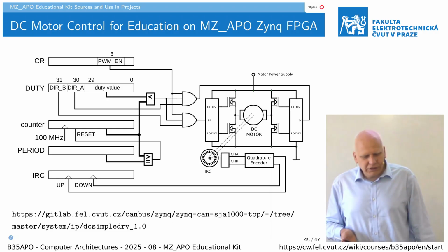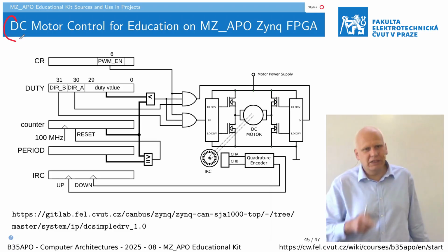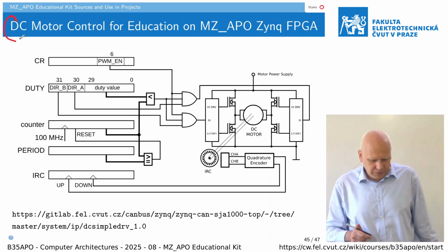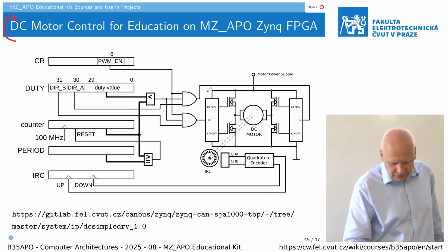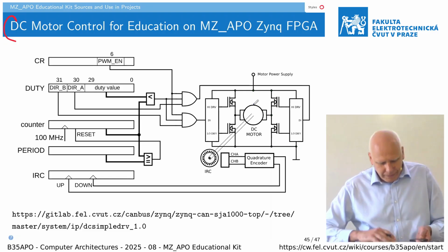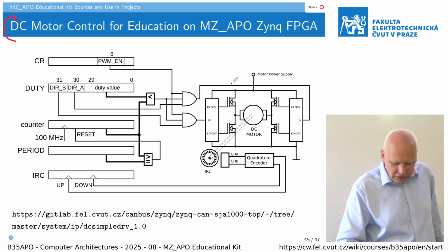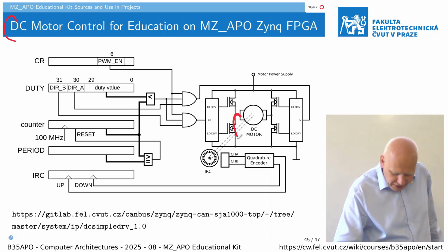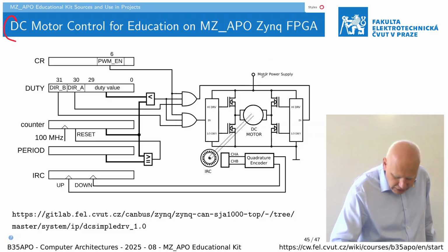You can use even that DC motors kits, which are available there in the shop. So you can use those to basically control the motor. If you have a DC motor, then basically you can connect both its ends to the ground, then it is stopped, or you can connect one to the ground and one to the power supply, this way.